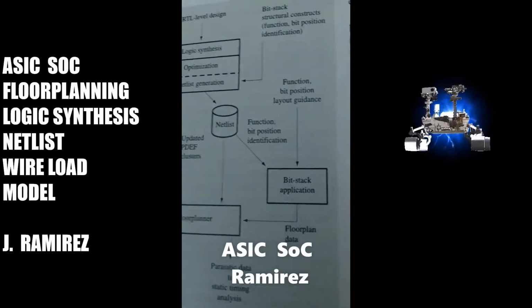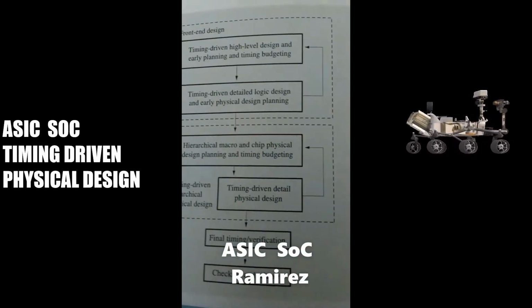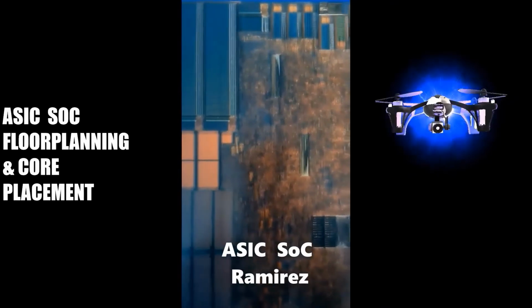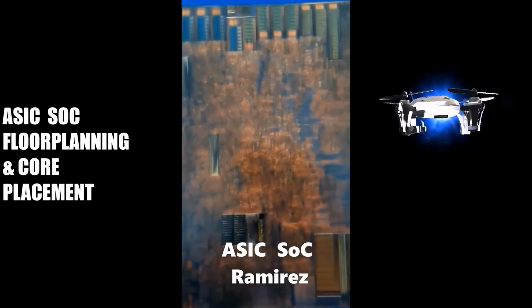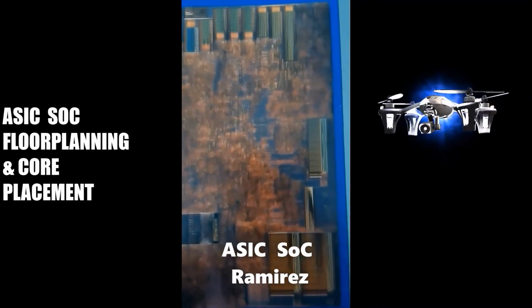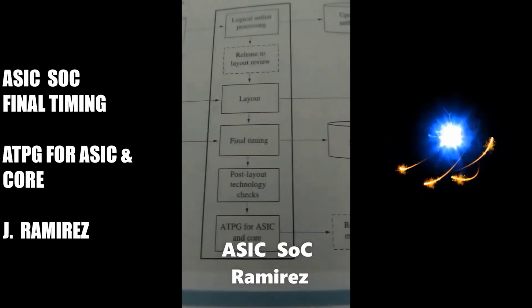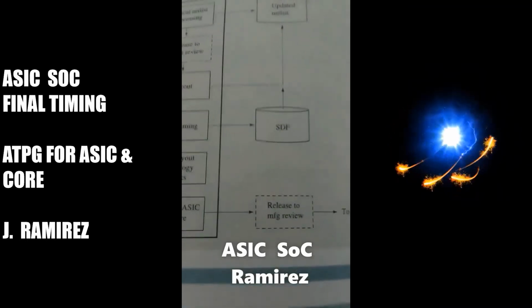descendants down the hierarchy that have rigid shapes, in order to fit each macrocell and its sibling macrocells into the parent macrocell in an effective way. The floor planning tool will have a range of legal shapes for each of the sibling macrocells.